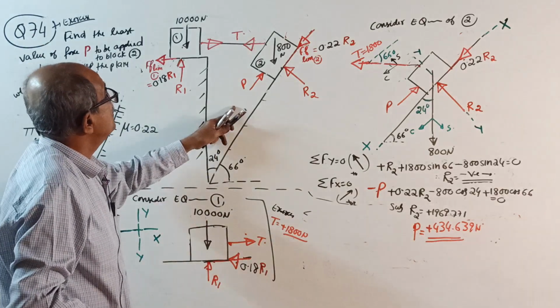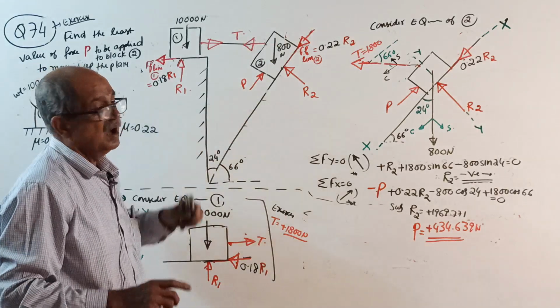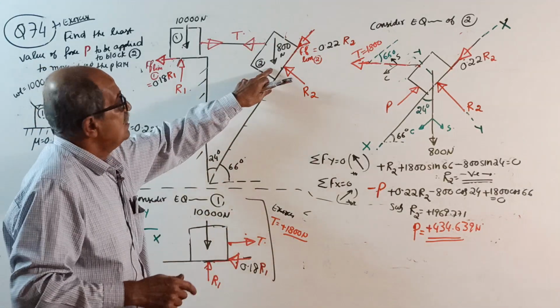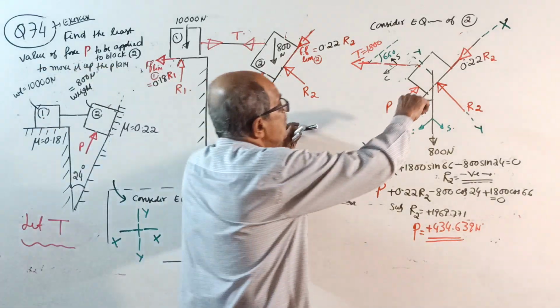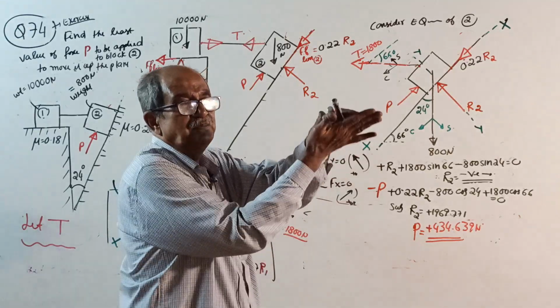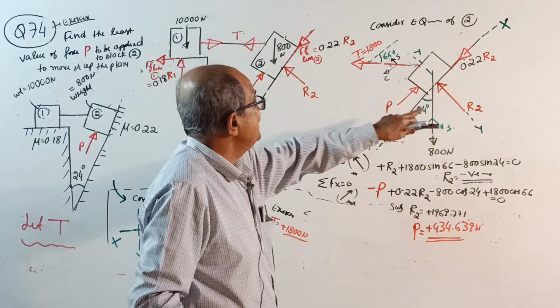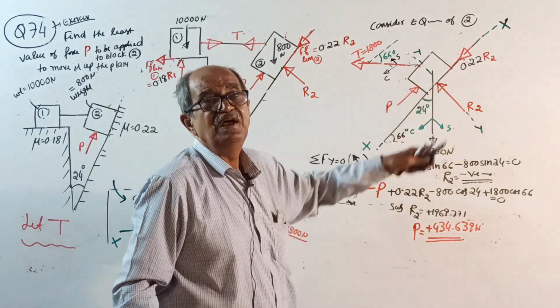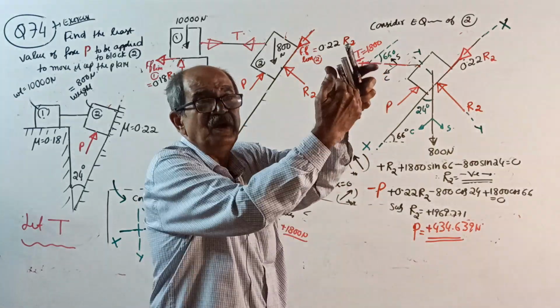It is not possible by applying a force this way to move it up the plane. Okay. Now, wrong answer. Solution does not exist because negative reaction is not possible. That is one thing guaranteed. See, when you place here, if you lift it, it will surface. For negative reaction, a hinge is required here. This simple support can give reaction only this way.